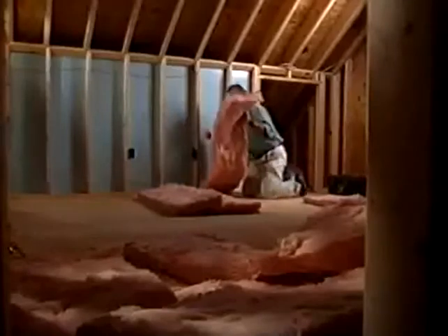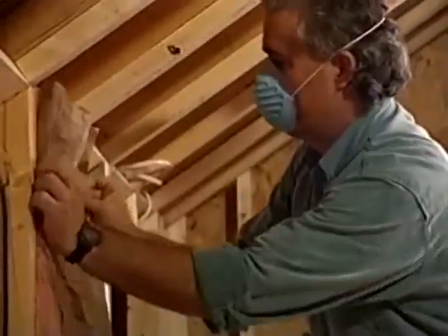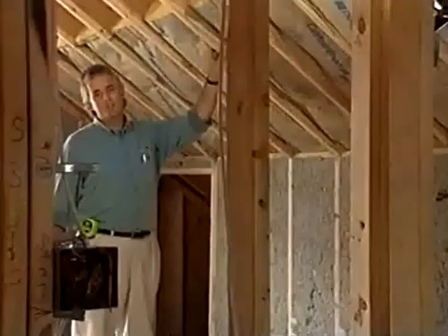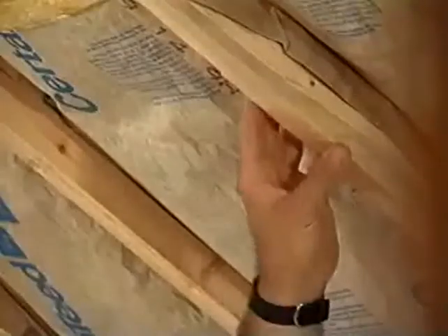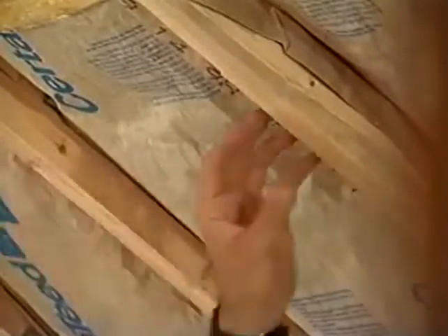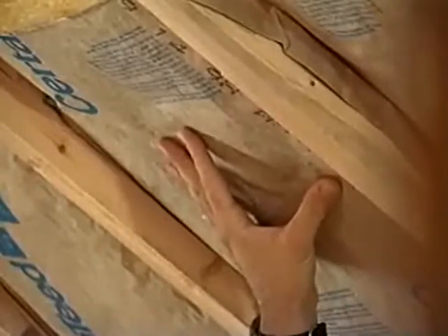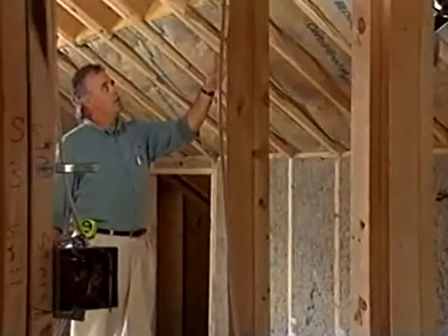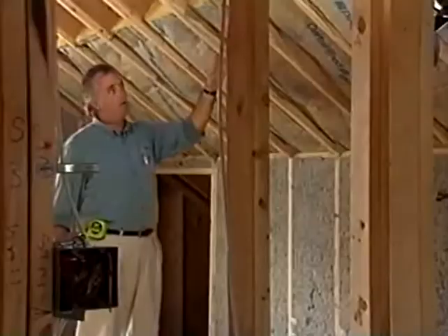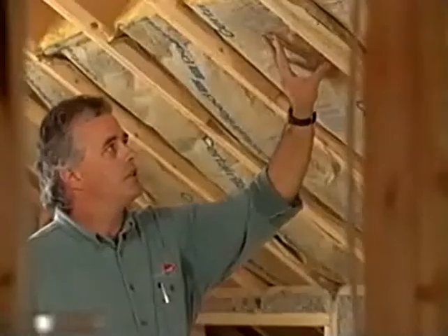Dan McFarland is a former insulation contractor and now works as a building science specialist. He says compression is one of the most common insulation mistakes. In this situation, the framing contractor has furred out this 2x8 an additional 1.5 inches. This will accommodate an R30 batt of fiberglass. But the problem is when the insulation contractor came behind him and installed his batts, he pushed them in too far, compressing them. Compressing the insulation means that they're not getting the full R value that they expect, and that they planned for, to have comfort up in this bonus room.